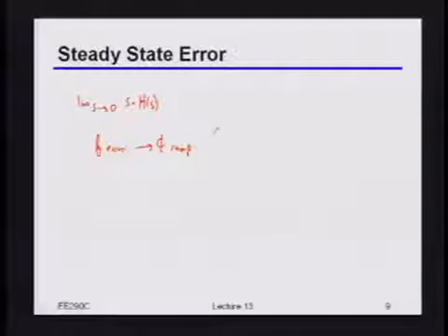Okay, now, just to get the dimensions right, it's going to be some frequency offset divided by s squared, right? Because that frequency offset tells you how quickly the phase accumulates, right? But that is indeed going to be your phase ramp. Okay? So now if that's the phase ramp, then as we said before, the CDR, let's just pretend that it's basically a first order loop, right?